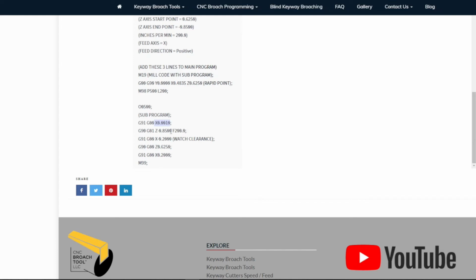And now your Z here goes down, but the thing you got to watch for here is your clearance. So every pass is going to retract back 200 thou on X. So if you don't have a lot of clearance on the back of your tool holder, you won't be able to use the subprogram style program. You want to switch that to longhand, because the longhand program goes to an absolute value every time, just slightly below the bore diameter, so it's a lot safer. You won't have to worry about your tool hitting the back side of the bar here.